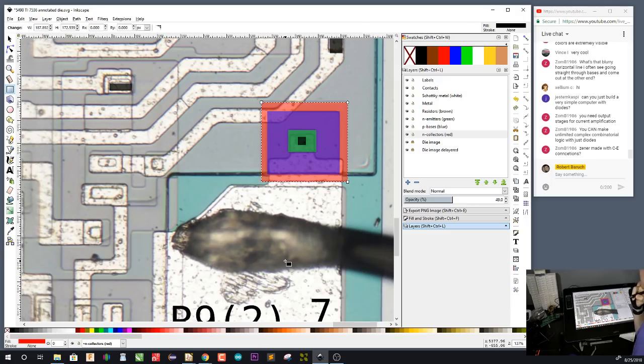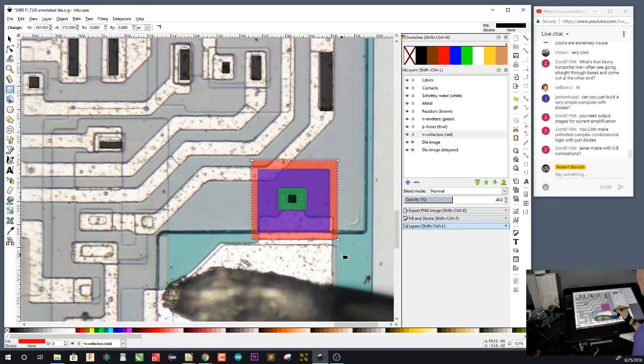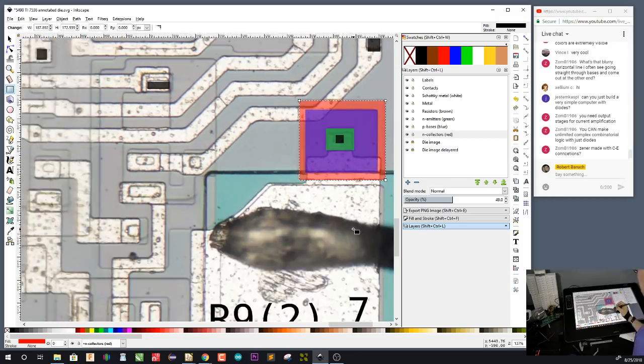You don't really see Zener diodes in TTL logic. You do see Schottky diodes, and Schottky diodes do look different in that they seem to have an extra bit of metal in there, because that's actually a Schottky connection. This is absolutely definitely a protection diode. I know that much. I'm just kind of blanking on how exactly the connections work.